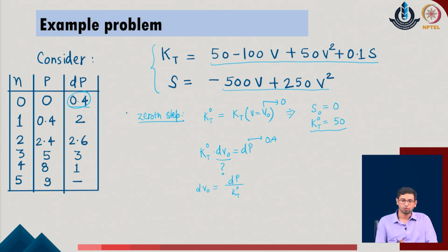In this given problem, we have only one stiffness parameter, only one load parameter and only one value of the displacement. But we must not forget that, in general, the procedure is prepared such that KT can be a generalized matrix, d of u can be a general vector of the given system, and d of p could also be a general vector. So, there could be more than one load active in the given system. We can have the increments in the load in the same manner or a different manner according to the situation, and according to that we can analyze the overall system.